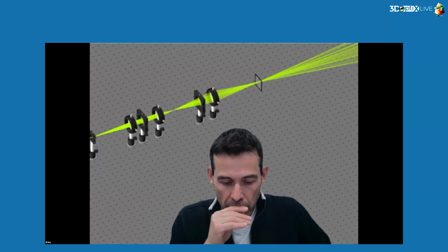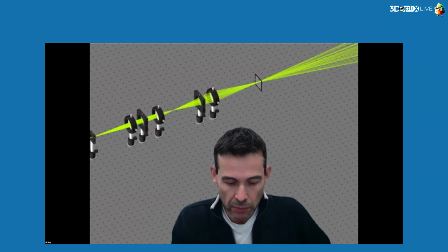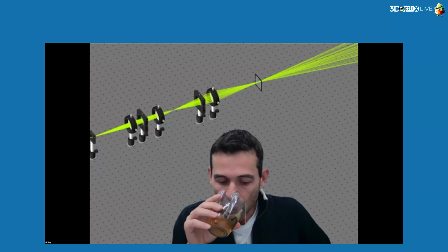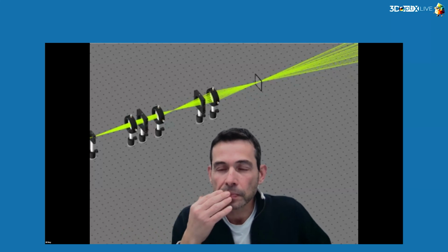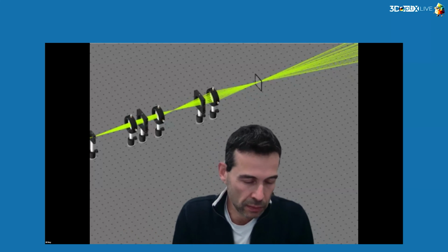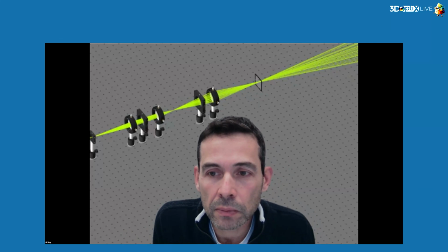What I really wanted to show is, if you had an unknown system or you wanted to optimize something for your application, how to do that step-by-step using some quasi-trace rays, moving the lenses back and forth and looking at it in the analysis window. So that's why I eyeballed everything. I wanted to show the versatility of using the application, but you can definitely position these perfectly.